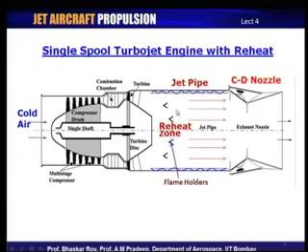So, you need to create a situation where the outer shell of the jet pipe is protected from this very high temperature inside. What you see here, this undulation, are essentially liners that are created to protect the body of the engine from the high velocity jet.